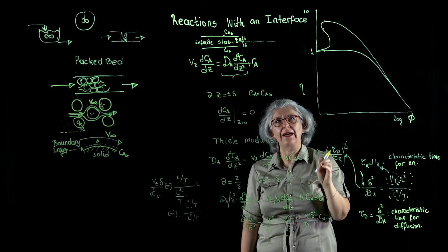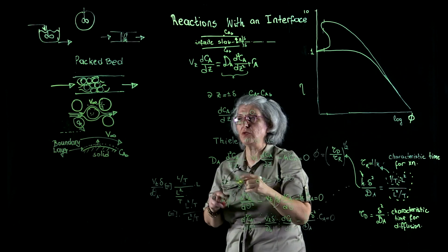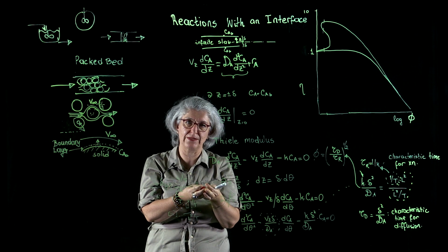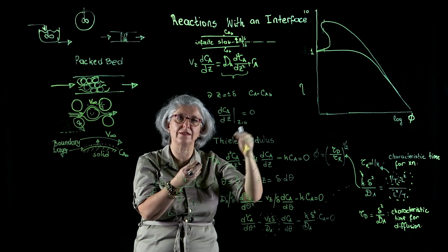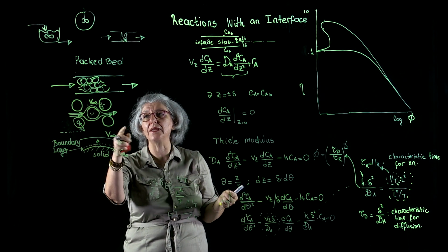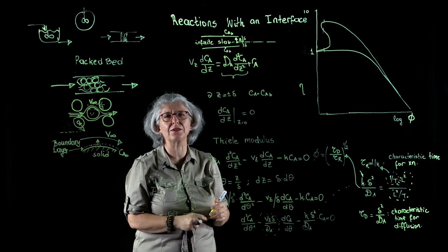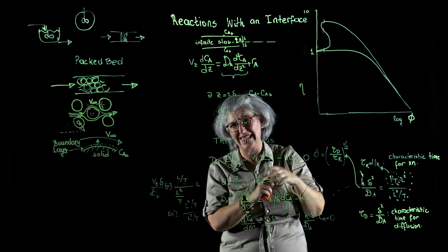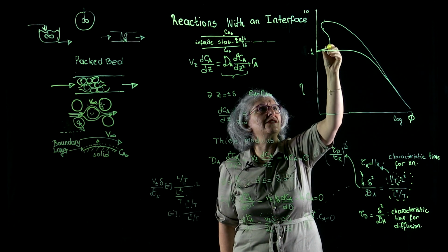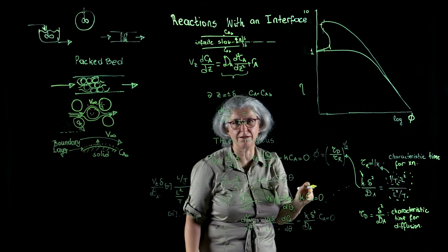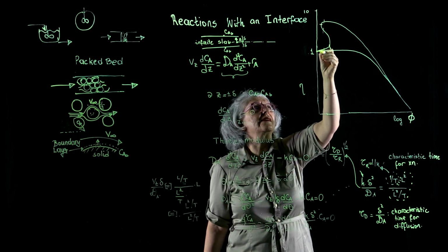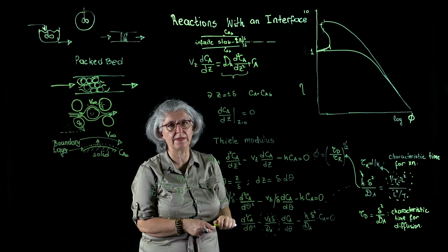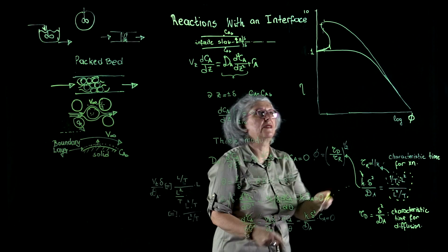So the multiplicity of these effectiveness factors are due to different zones of temperature in the catalyst particle. Outside the surface, the system is thermally equilibrated with the environment. In the middle of the catalyst, we have very high temperatures, all right, and then we have strange behaviors of effectiveness factors increasing with decreasing Thiele parameter. These domains are domains of instability, but we have some meaningful behaviors of effectiveness factor as a function of Thiele parameters.